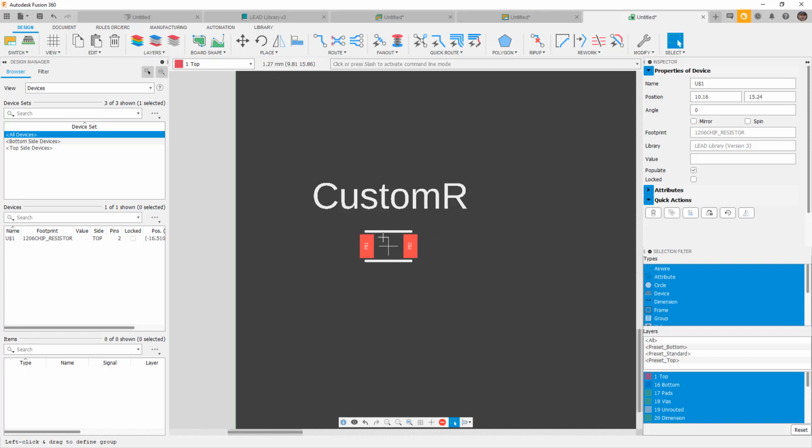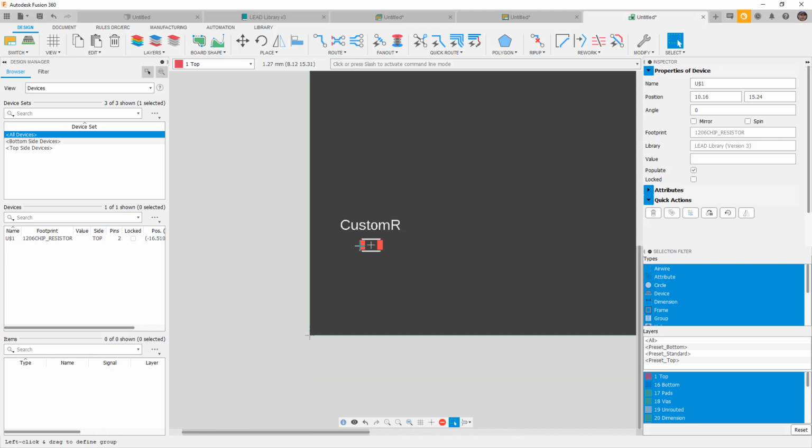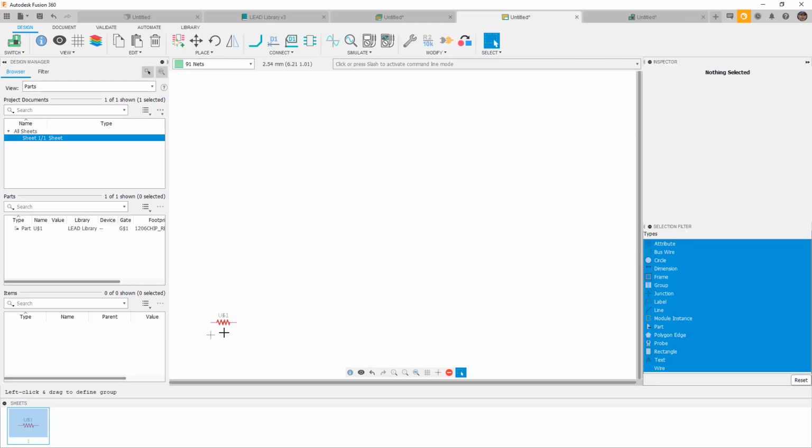It has our lines, and it has our 2 pads. And those pads are connected to what we saw on our symbol. Now remember, that's the important bit, because when we start creating nets, they're going to allow us to draw between the pins on our symbols, and it'll transfer that when we go into our circuit board in the PCB, and it'll understand what those connections mean.